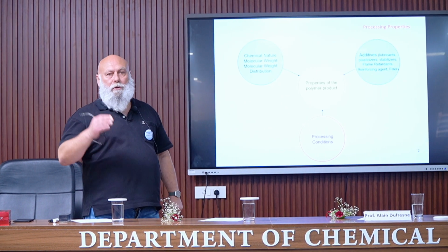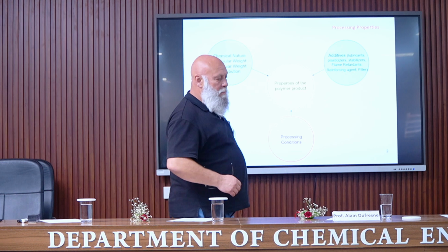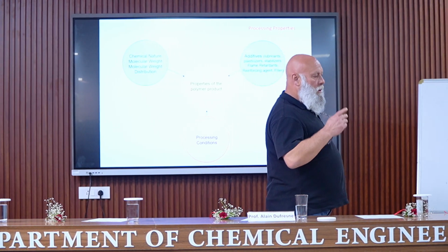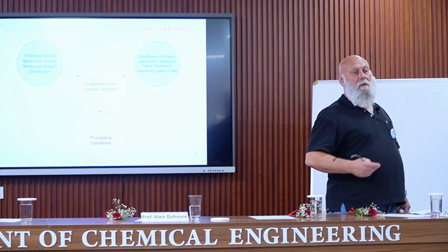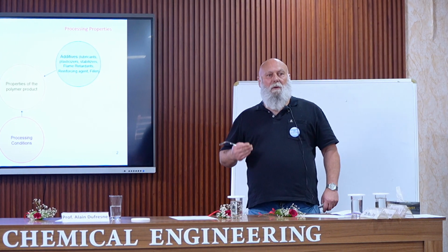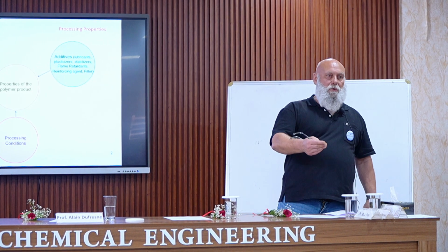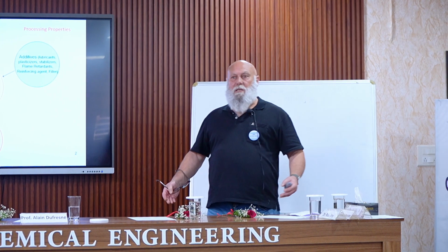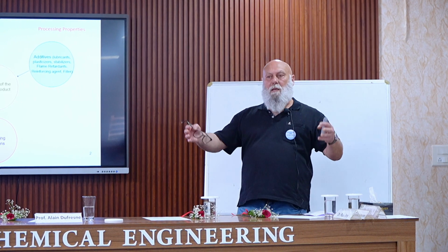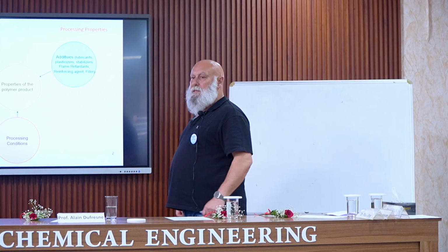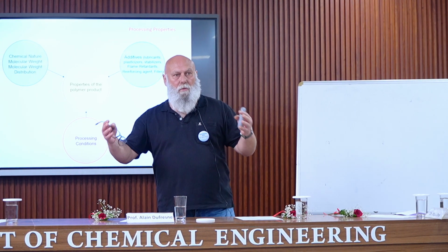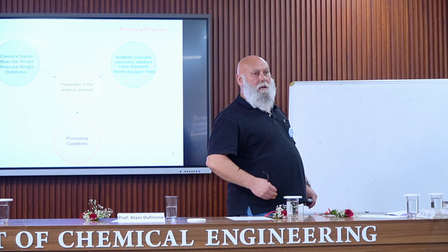And the other condition is to have good interactions with the polymers that we want to plasticize. So the objective, of course, is to homogeneously distribute this plasticizer molecule in the macromolecular network in order to limit the interactions between the macromolecules.